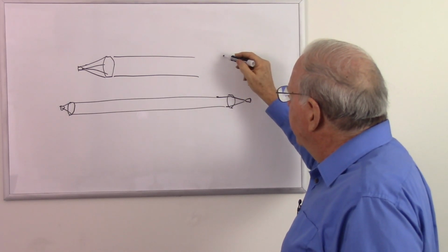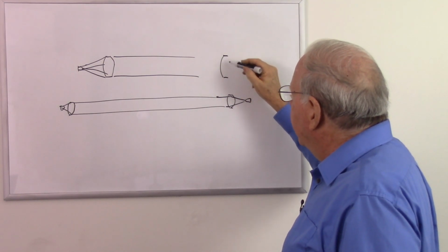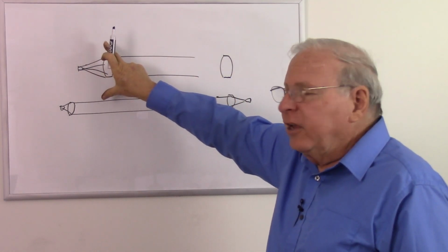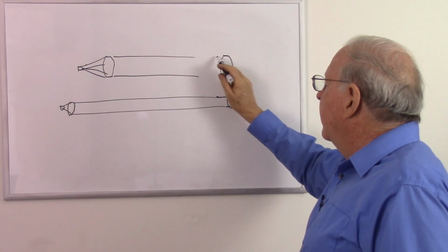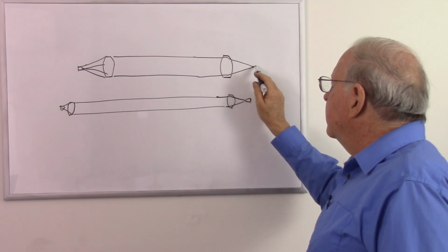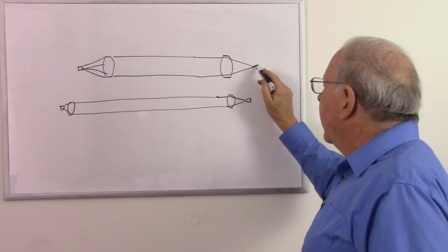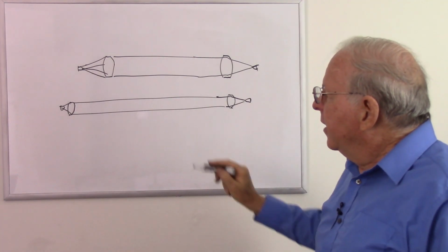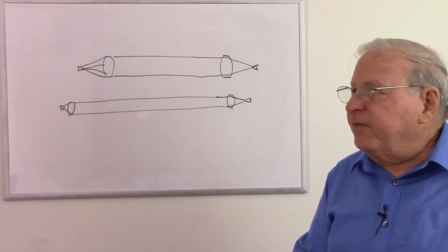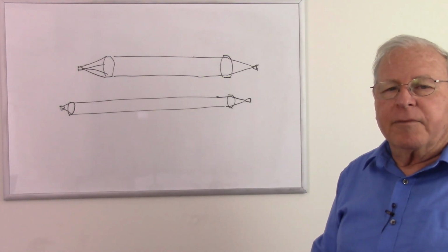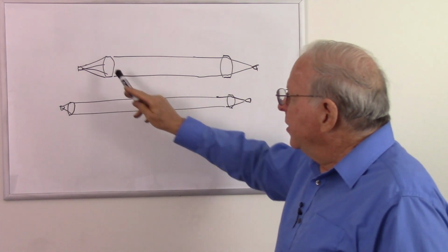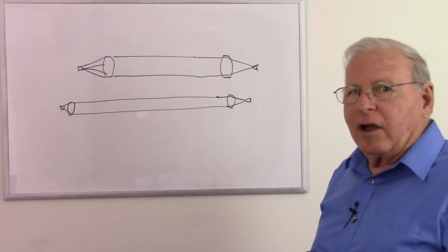And then what we need to do here is do the opposite of collimating, which is going to be to converge that. So here it diverges, then we want to converge it again, and actually we usually would say we focus the light when we converge it on the photodiode over at the other end. So the light going through there is collimated. And when we talk about laser in the next video, we'll talk about one of the important things about laser light, it's collimated. But we can collimate light with a single lens, and that's how we would do that.